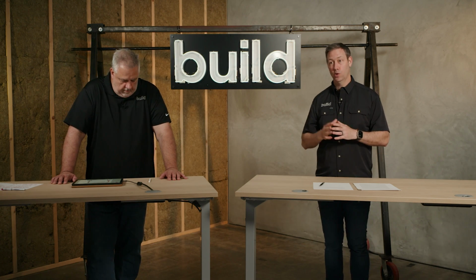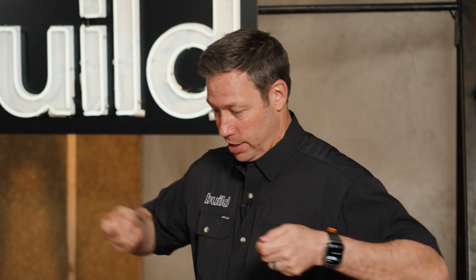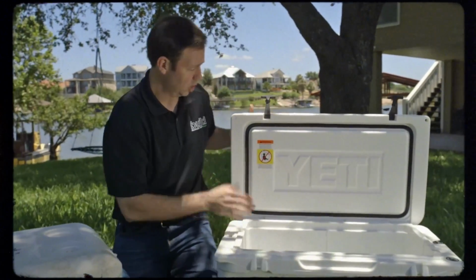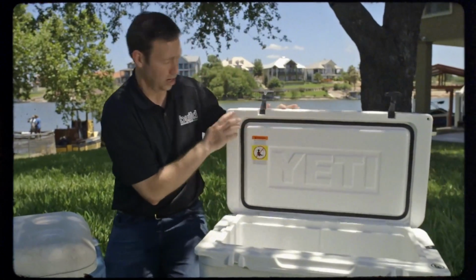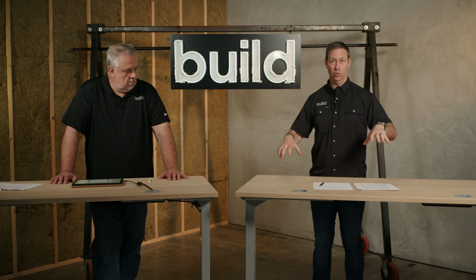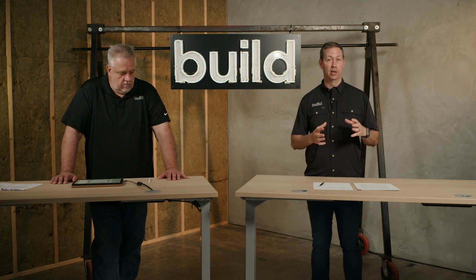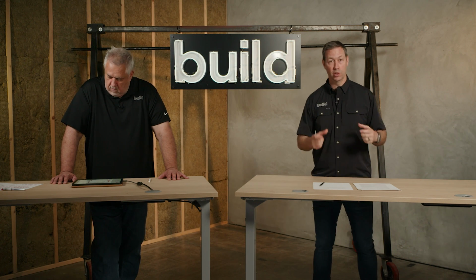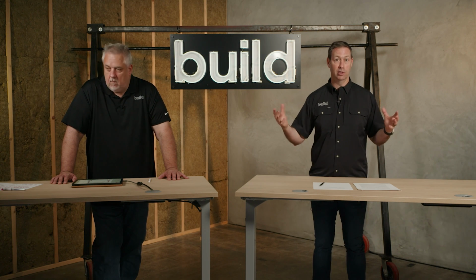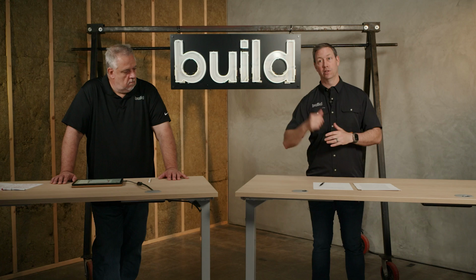The key to Yeti coolers is closing the lid, and they've got these latches that really push it down against the gasket. And if you look at the top lid on a Yeti cooler, there's this big gasket that runs continuous all the way around the lid, so that when the lid is closed and you push those two rubber levers down, it seals it really, really tight. So the key to that high performance cooler is good insulation and good air tightness. And as Steve mentioned, that insulation doesn't do anything if the lid is open.